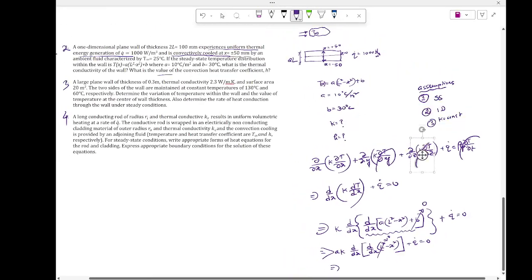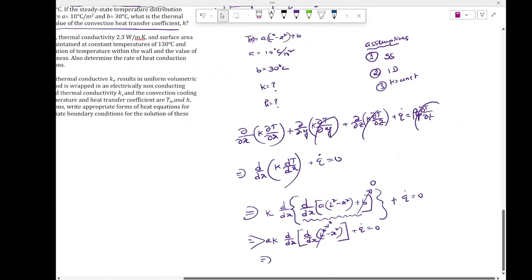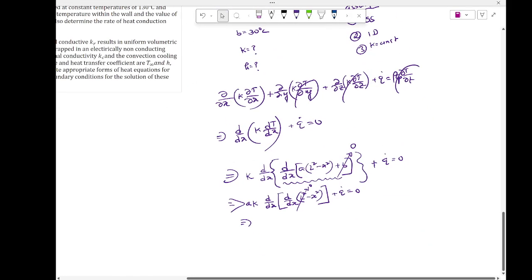What is the value of the convection? I mean, once we have the K, then we can find the conduction. And the conduction equals convection here, if there is no radiation, right? Isaac, you just have to assume that radiation. Think this way, Isaac. If this is the block that we're talking about, this block has the conduction happening. At the surface, convection and radiation can happen, right?